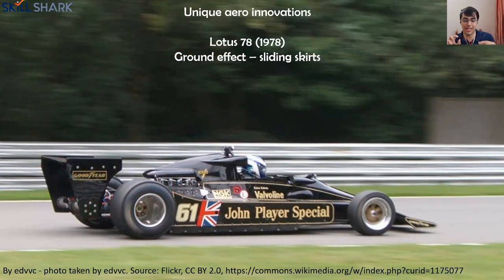More in particular, it was actually at the edge of the underbody, and they were mounted on springs that were attached to the chassis. So effectively, it closed the entire underbody. So instead of air leaking out from underneath, it would seal that point. And what that does is it accelerates the flow to a much higher speed, and it's more controlled underneath the car. So these cars were able to reach absurdly high levels of speed through corners because of how much downforce they had. Great innovation, of course, but naturally it got banned because, for one thing, it is unsafe to have cars that can go that fast.